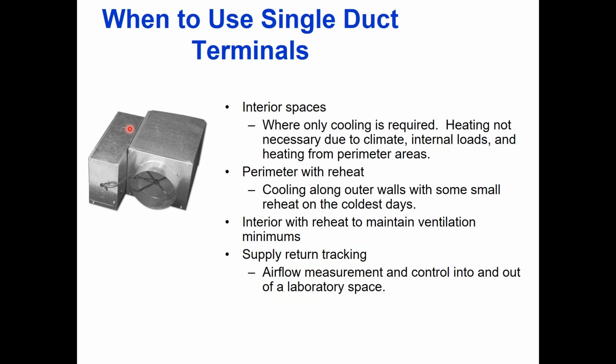So if I was to take this box and I was going to use it for a perimeter zone, now I'm going to want to add a reheat to it because that perimeter zone is going to have an exposed wall. So I'm going to need to heat that. Sometimes on interior zones, we might have a little bit of reheat if I'm going to have a lot of outside air.